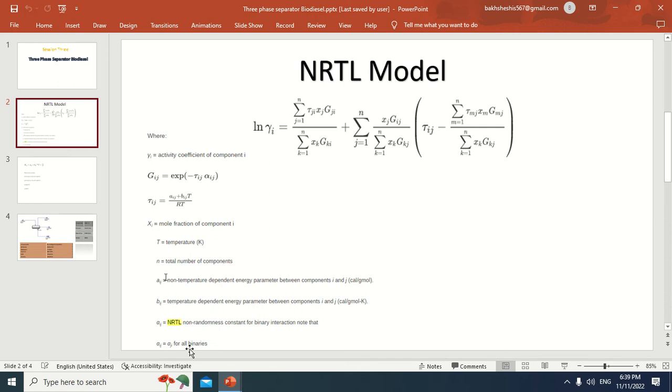The equation has parameter values stored in HYSYS, or any user supplied value for further fitting the equation to a given set of data. And I want to talk about units. The energy related parameters in the NRTL model use units in agreement with the unit of gas constant R.